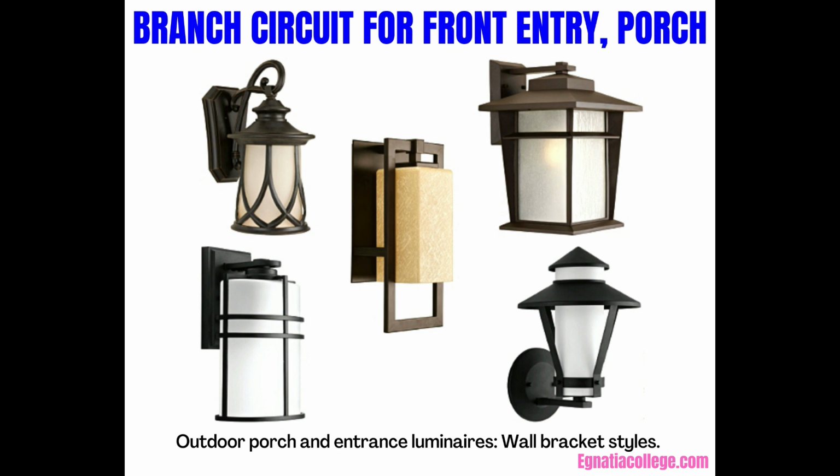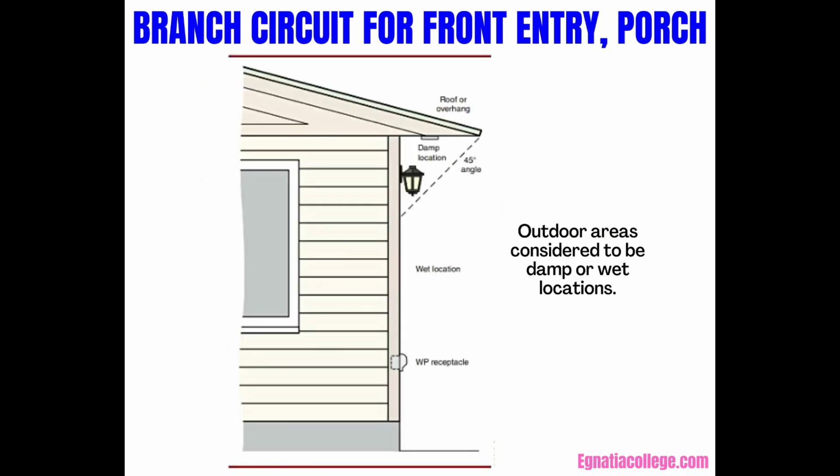According to Rule 30-318, any wiring of light fixtures in damp or wet locations requires fixtures to be approved and marked for use in such locations. For example, the fixtures will be marked suitable for wet locations. The CEC defines partially protected areas under roofs, canopies, or open porches as damp locations. Fixtures to be used in these locations must be marked suitable for damp locations. Many types of fixtures are available. Always check the label on the fixture for CSA approval or consult with your electrical supplier to determine the suitability of the fixture for a wet or damp location.